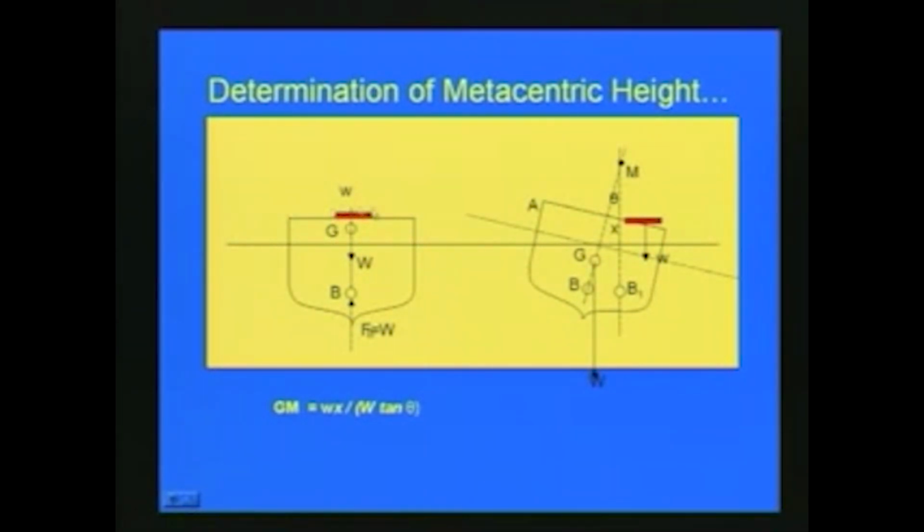So, when it is in this position, it is in stable equilibrium and there is no tilt. When we shift this small load to one side, you can see that there will be a tilt, a displacement for the floating body like this. You can see a small angle of tilt, and this is the new position of this horizontal line.